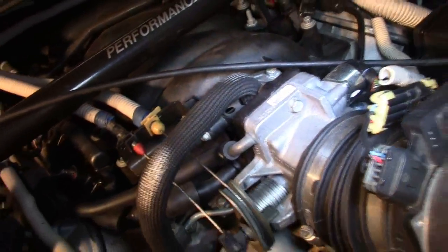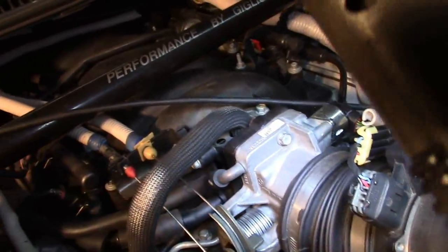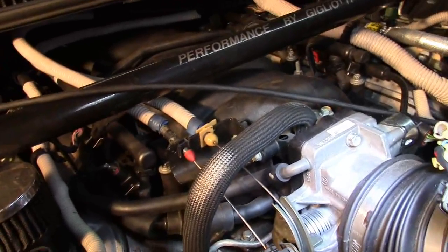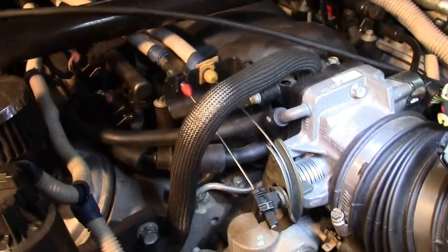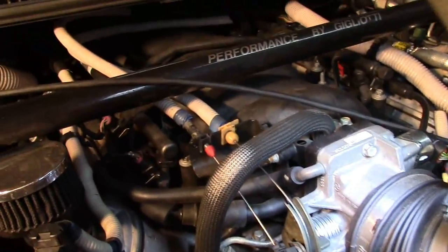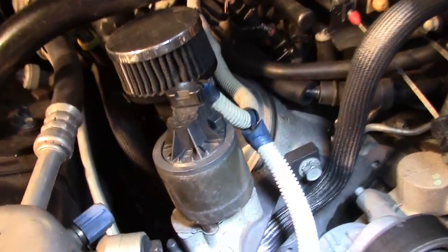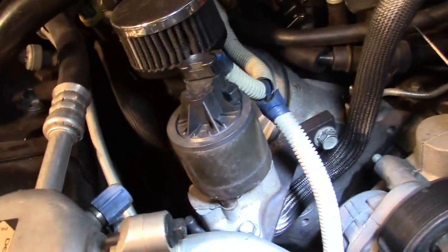This tube up here goes to the intake, and I know we haven't covered EGR. We'll cover that on another diagnosis and understanding. But based on our understanding of the system, there is no reason we would have a tube going to the intake manifold on an air system. So even if we didn't know that this was the EGR, we would dismiss this.